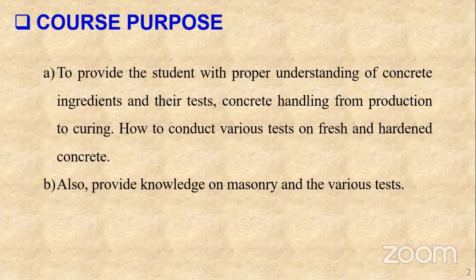You realize that you have good quality sand, good ballast, the water you are using is okay, the ratios are okay, but maybe during the mixing, the quality control, maybe the ratios, something happened, too much water was utilized, so that the end product, you do not get to attain the strength that you required.